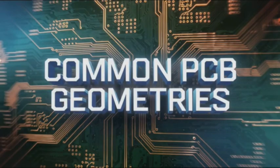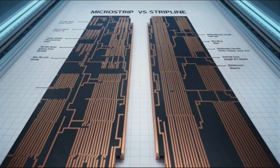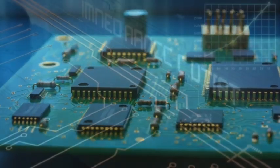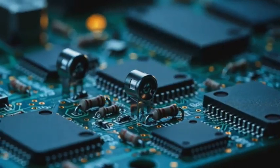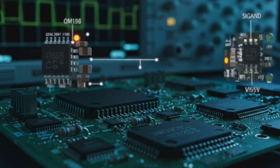Common PCB geometries include microstrips, traces over a ground plane, and strip lines, traces between two planes. Trace dimensions and dielectric properties directly affect impedance, critical for EMC management. Consider this mixed signal system: sensor feeding amplifiers, ADCs, and a microcontroller.